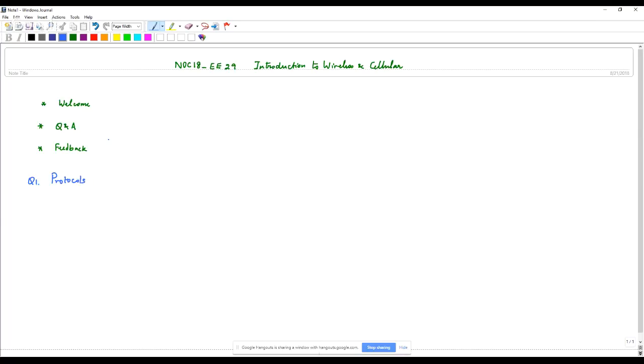Now, if you recall in the introductory videos, in week 1, we saw how a GSM call is made. So there is the aspect of signaling. Even before a call is established, there's a lot of information that is shared between the mobile and the network, and also the location identification of the network. So there is signaling, and the signaling also addresses the issue of mobility, locating the user, and then informing the user about the incoming call. So call notification. And then finally the call setup, the final step of setting up the call.